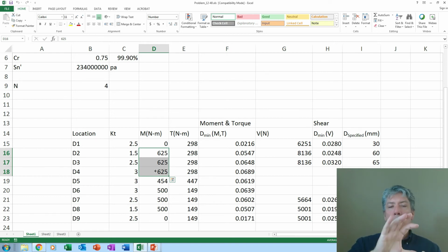They could have chosen a much taller capacitor. They could have chosen a larger diameter capacitor, and it would have been cheaper and been more reliable, because generally as capacitors get smaller, they get less reliable. Manufacturers try to pack as much into them as possible. And so always choosing the highest performance part, or the highest performance material by analogy here, isn't necessarily what you want to do. That just adds cost when it's unnecessary.